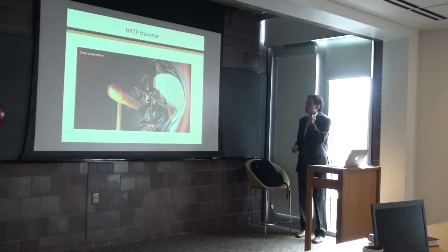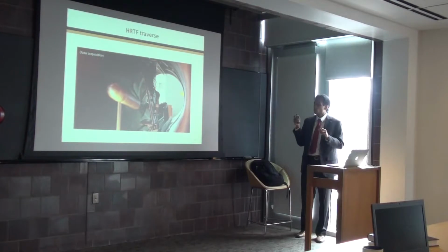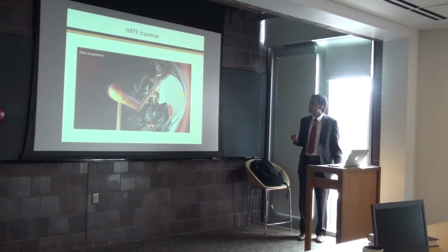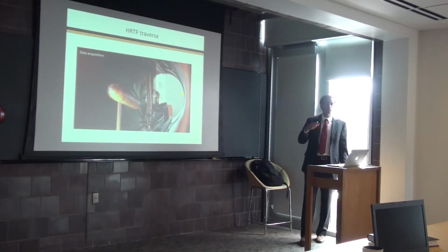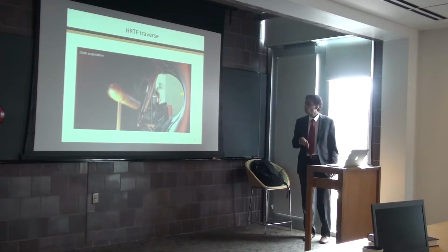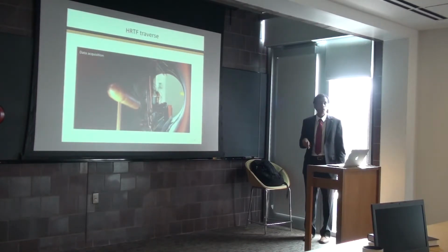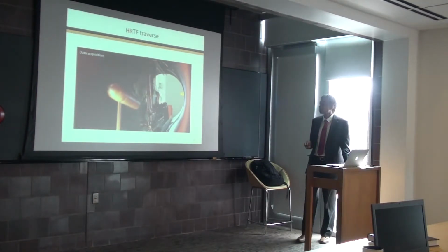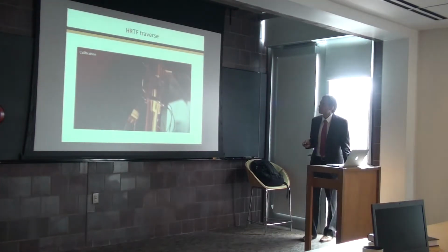So if I play this little animation, the traverse, this is all controlled by a LabVIEW program outside of the wind tunnel. The traverse is now zeroing itself. Of course, I know where the wake is because I performed these experiments before in the low-speed wind tunnel. So I tell the computer where to put the probe, and off it puts the probe in that location, takes data, and moves on its merry way. And this is how we take the data.